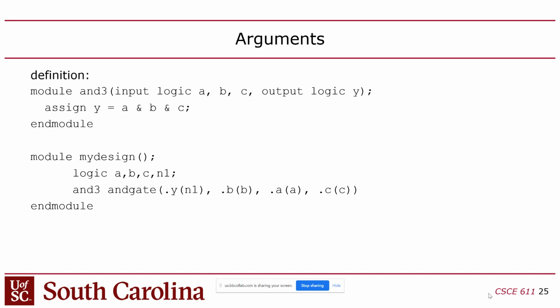But the name is just basically for the simulator's sake. So you won't even refer to this name in your code because all of the interactions you do are through its IOs, right? So you will never actually type out this AND gate thing again. But anyway, I called it AND gate. So this is the module, that's the instance name.